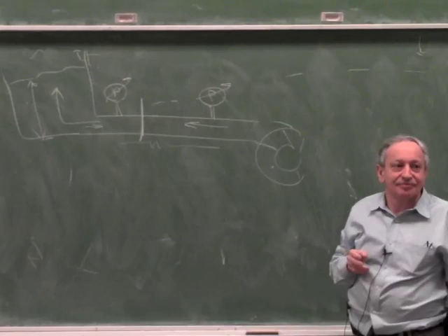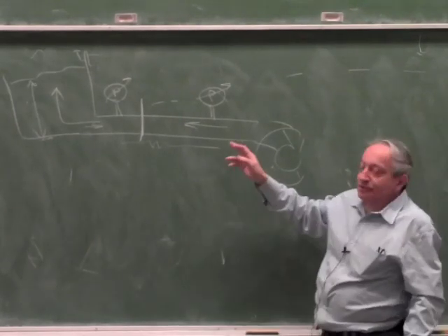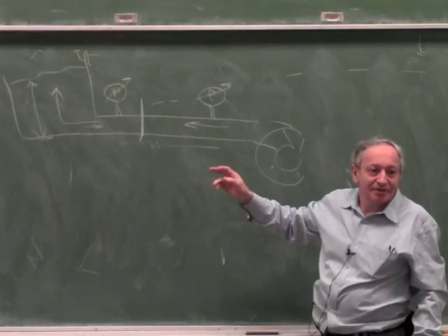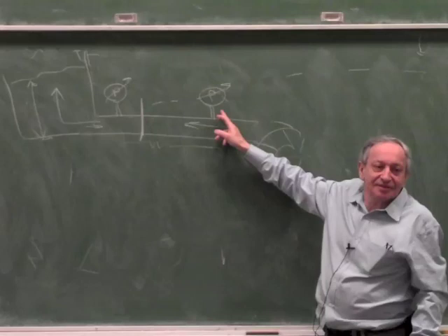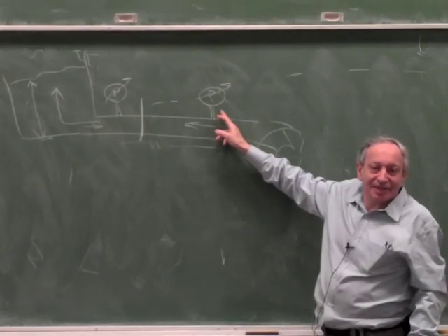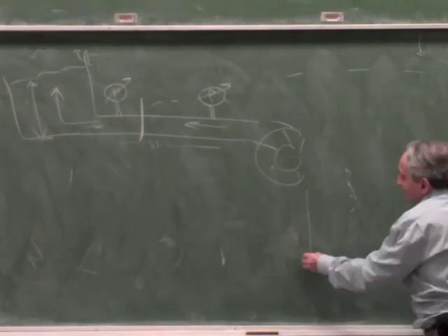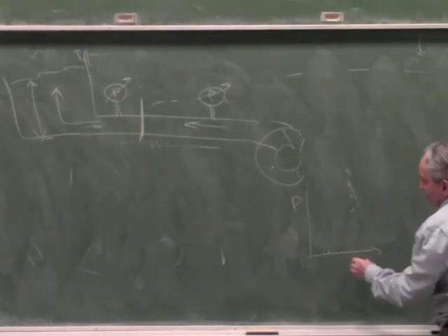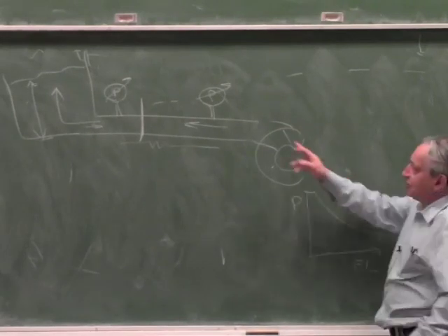One will rise and one will drop. Which will rise, which will drop? The one on the pump side will rise. Now, why would it rise? Because it has all this flow that's compressing. Yes, because the pump has some graph of flow versus pressure, and most pumps, if this is pressure and this is flow, have a graph like this, so if the flow goes to zero, the pressure goes up.